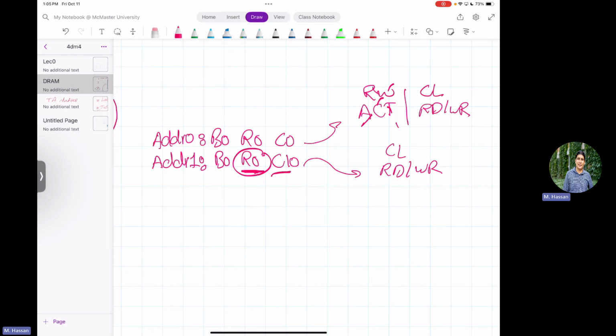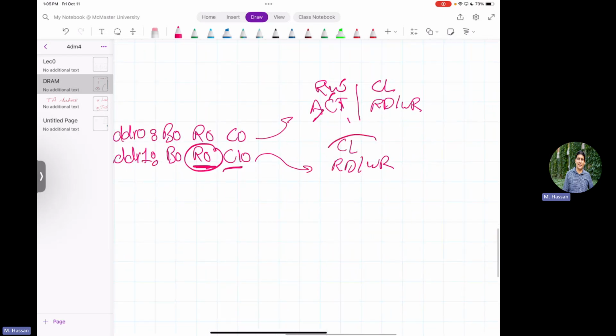So most of the DRAM scheduling we will see in the memory controller, likely after the reading week, is about minimizing the number of times you need to activate new rows. It will do a lot of request reordering so that once you bring a row into the row buffer, you keep hitting into it and maximize the number of hits. Good. So this is a best case scenario because you only need to do one of the stages, not the two stages. So you save a lot of time.